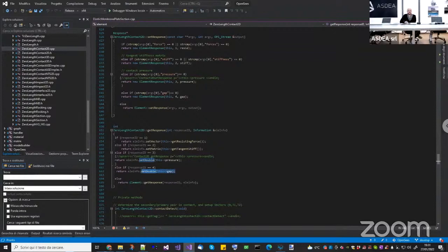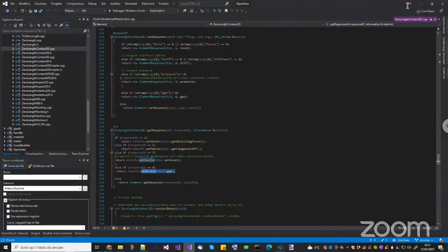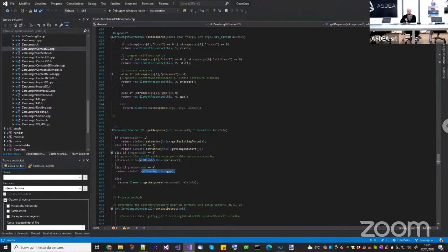So if it is in Python, okay. The point is that I understood you developed a new element, but it's not actually a new element in OpenSees. It's a collection of existing elements in OpenSees. The point is that you can add some elements, so you can customize what STKO is going to write just by using a custom command. Not by changing the TCL file after you generate it, because the next time you generate the TCL file, your changes are lost. So the other option instead for you would be to create a custom command.